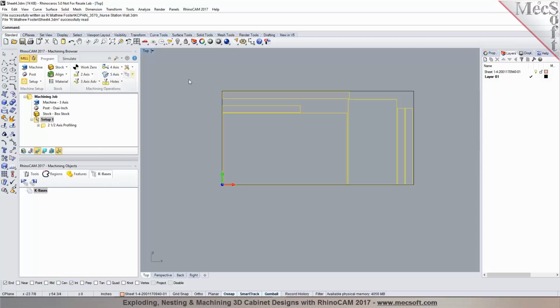Once you export them as curves, you could then go ahead and establish the nesting process by going to the nesting module to nest them into a sheet. And once you have them nested, you can either export the nest to separate files, or you can export them all into the same file and then process your toolpaths.